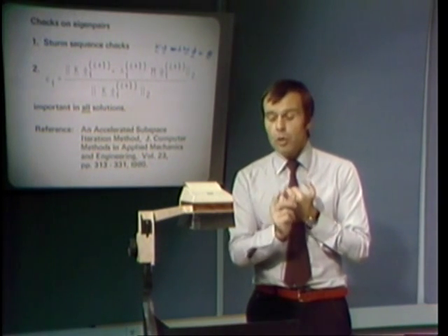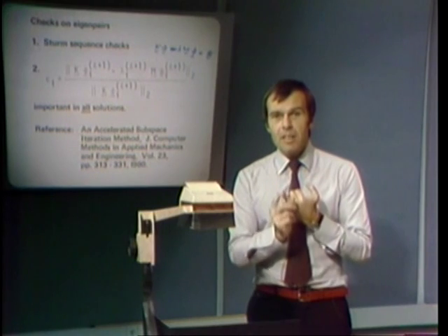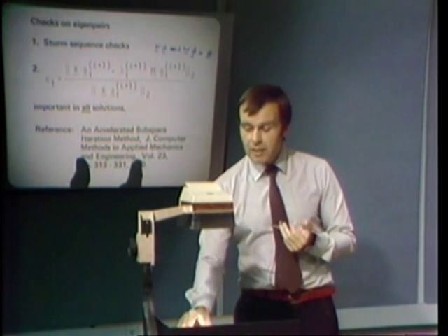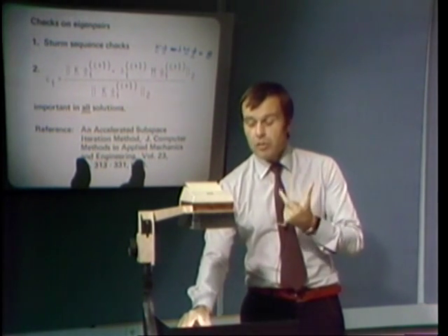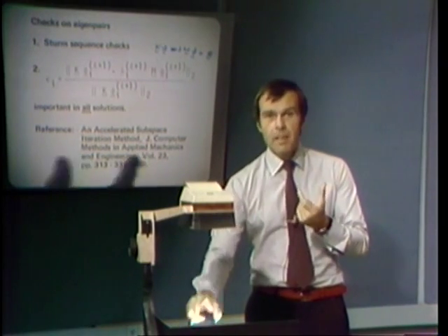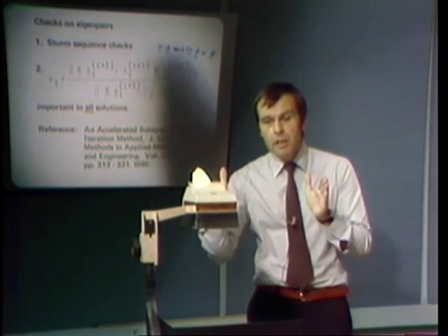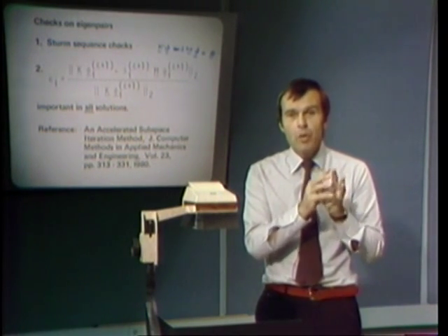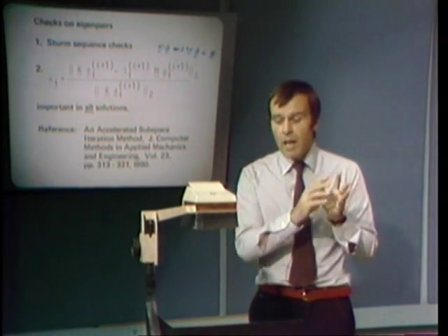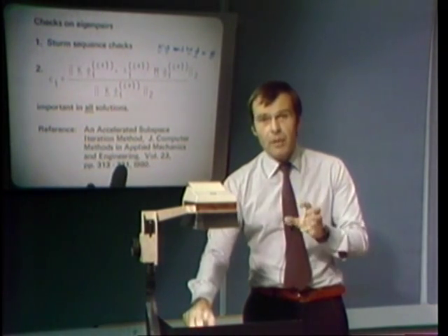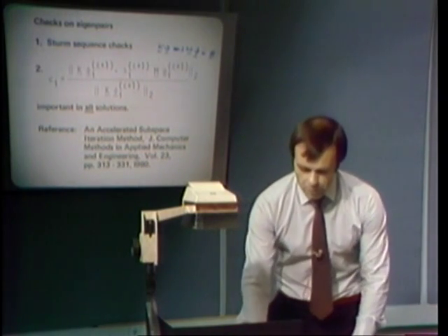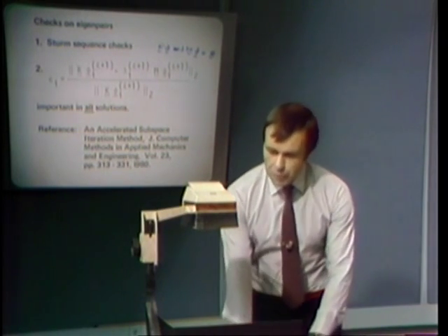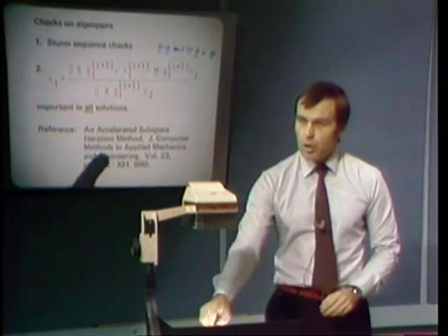And number two, we are also not iterating with vectors that are always larger than the number of eigenvectors that we want to calculate. In fact, if we want to calculate here, say, 100 eigenvalues, we might just use 4 iteration vectors at a time and shift through the spectrum, always with 4 iteration vectors, capturing the eigenvalues and eigenvectors that we are really interested in bundles. So this is a way how we have very substantially accelerated the standard subspace iteration method that I have been talking to you about just now. If you are interested in seeing some solution times, please look at this reference.